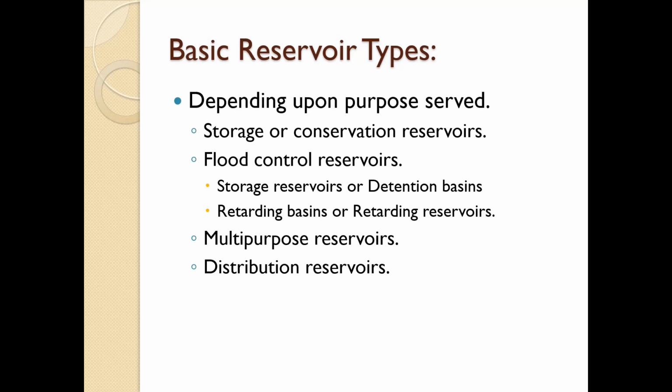Now, the functioning and advantages of storage reservoirs. A storage reservoir with a gated spillway and gated sluiceways provides more flexibility in operation and thus gives better control and increased usefulness of the reservoir. Storage reservoirs are therefore preferred on large rivers, which require better control, while retarding basins are preferred on small rivers.